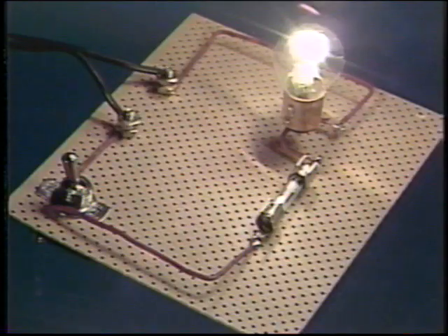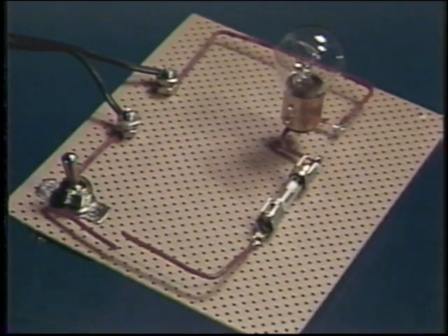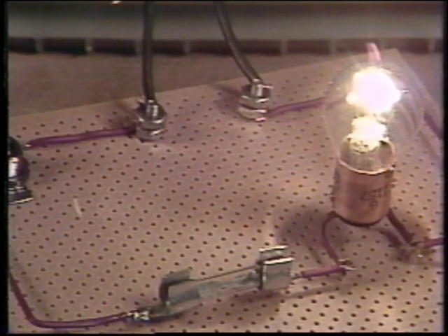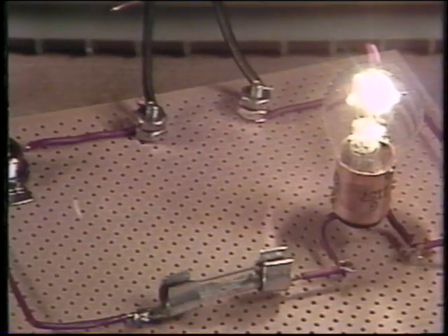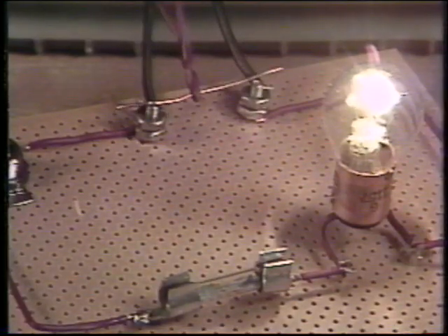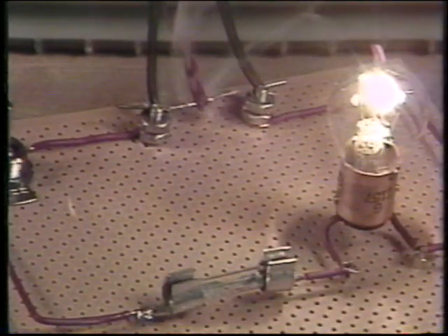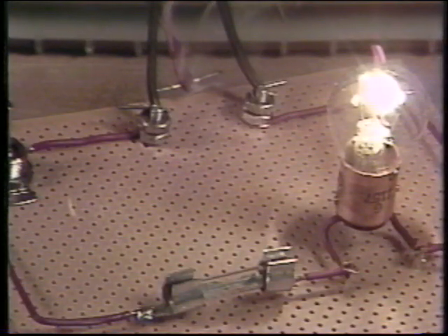An open circuit is one that has been interrupted either by a switch or a break in the circuit or one of its components. A short circuit is one in which a current-carrying conductor contacts another conductor, bypassing the load and creating a shortened path back to the source. Short circuits are hazardous in that they may carry large amounts of current which may exceed the current carrying capacity of the wire. Short circuits often overheat electrical wiring and cause electrical fires.